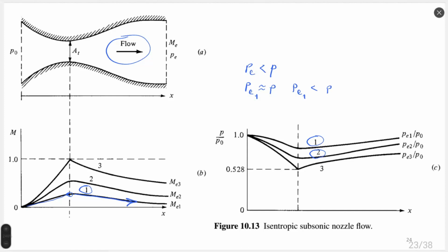So the flow becomes compressible, Mach bigger than 0.3 at this point. But compressible flow does not mean that it will be supersonic. Compressible and supersonic are two distinct definitions. Compressibility does not mean that the flow will become supersonic. If the flow energy is not enough, if the potential is not enough for acceleration, we cannot accelerate. The flow will still remain subsonic.